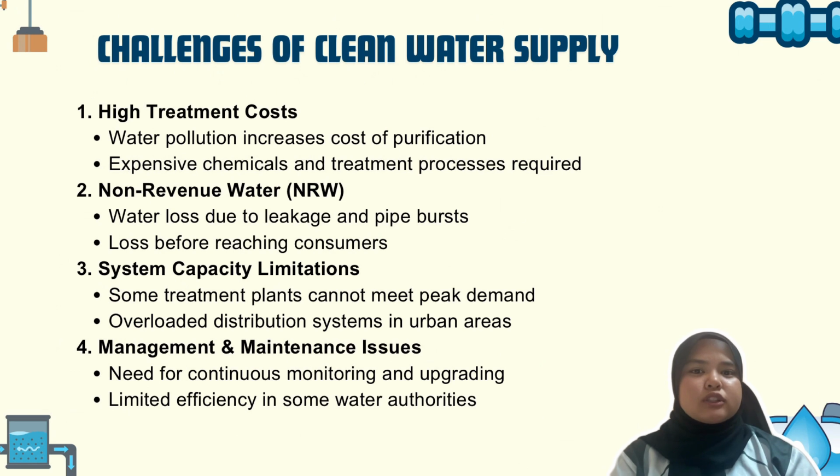First, high treatment cost. Clean water treatment is costly because polluted water needs more chemicals and better treatment processes to make it safe. Second, non-revenue water or NRW. Water is lost due to leaking pipes and pipe bursts before it reaches consumers. Third is system capacity limitation. Some water treatment plants cannot provide enough water during high demand,